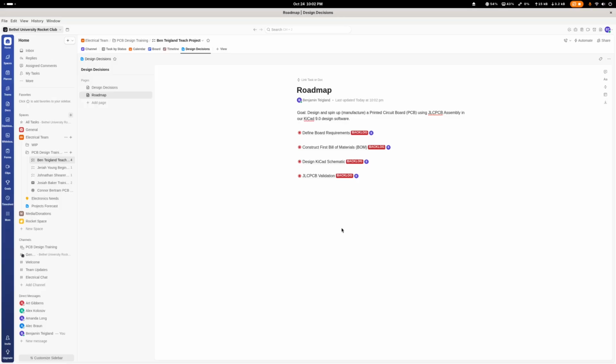It'll be another chance to look at the bill of materials to make sure that's right. We're going to make sure we have all the part numbers attached to the symbols and make sure they're all formatted so we can just export a bill of materials really easily, straight out of KiCad. Don't have to mess around with anything.